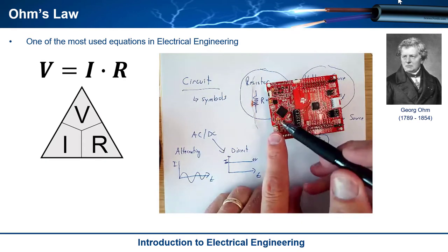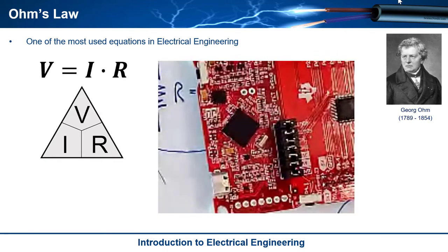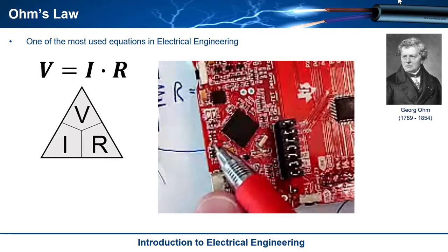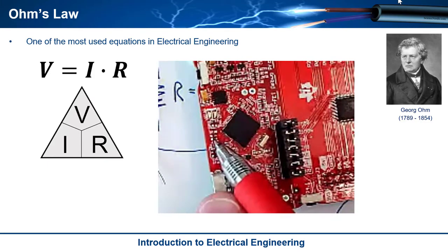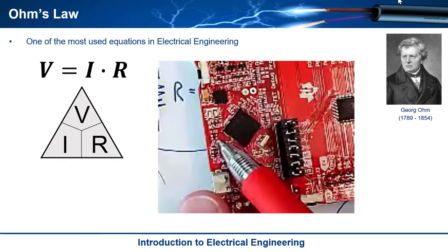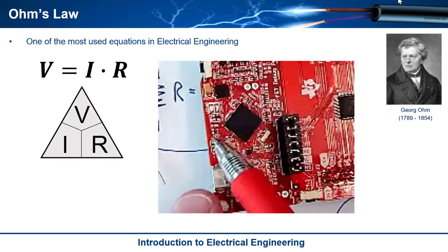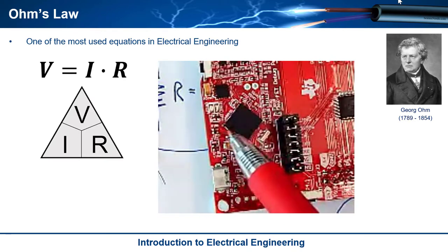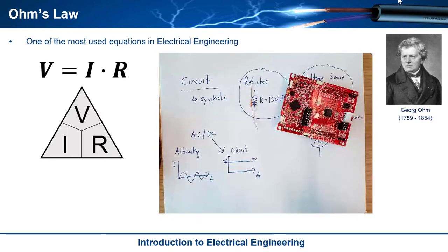So for example, when you come in here, these little fellas right there, I know they're kind of hard to see, but they're little tiny resistors. They're 60 thousandths of an inch by 30 thousandths of an inch, or 40 thousandths by 20 thousandths. They're the same thing though. They have 2 terminals and a value of resistance, and we can calculate the current through them when we put a voltage across them, knowing their resistance. So these things are real components.